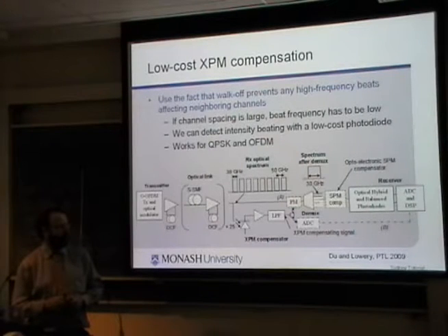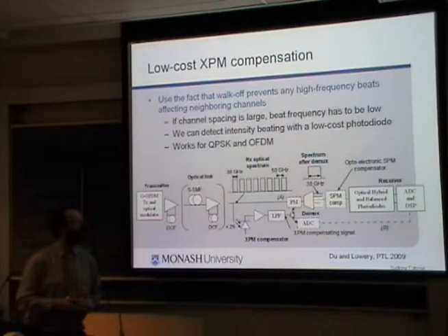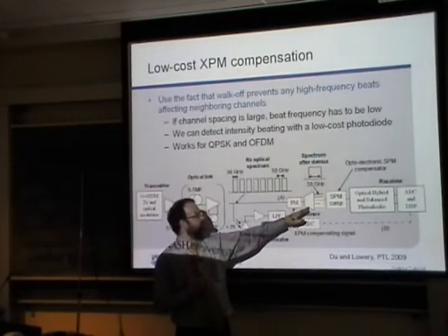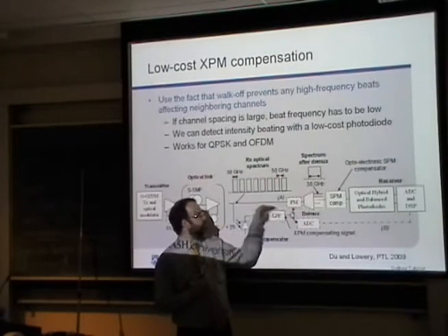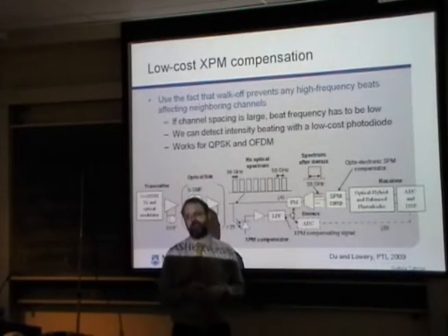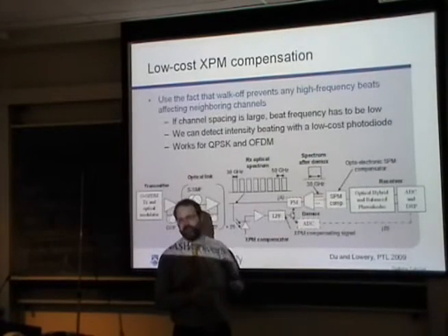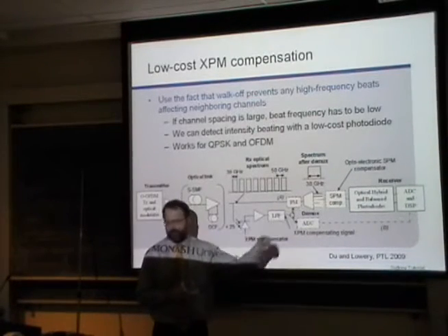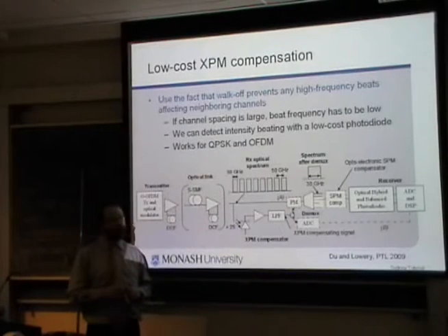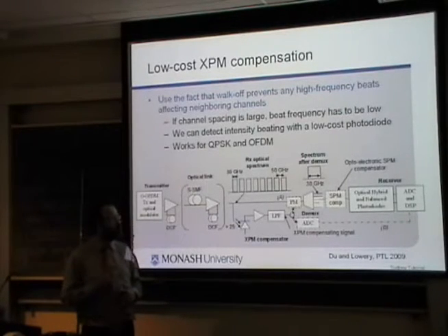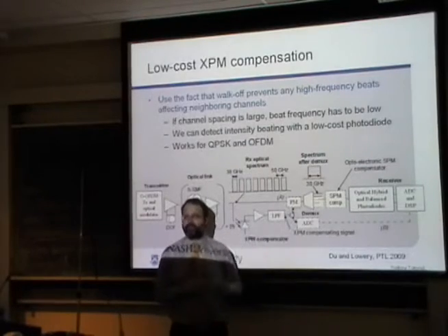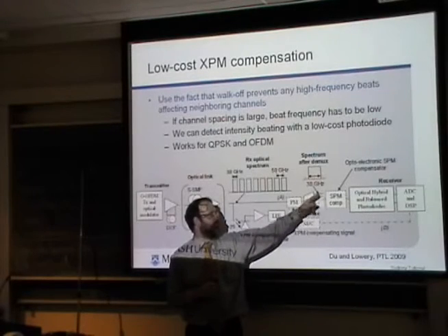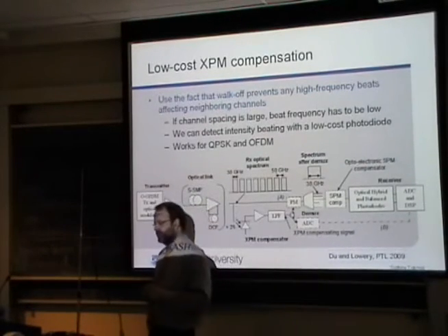However, there may be some advantage of doing Fourier transforms optically. And indeed, this demux is often designed to be discrete channels. So you put in a signal, it splits it between discrete channels. If you replace that with an optical Fourier transform, you'll get the ability to pack the channels closer together. So redesigning that optical filter is an interesting thing. And to make a proper Fourier transform, it ought to be a filter followed by fast optical sampling. So optical sampling might be useful after that component.